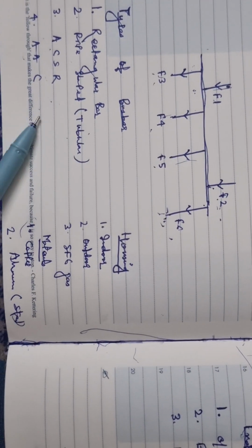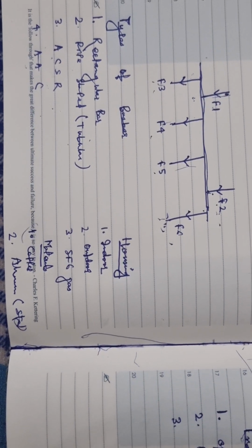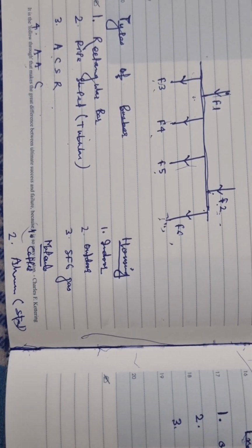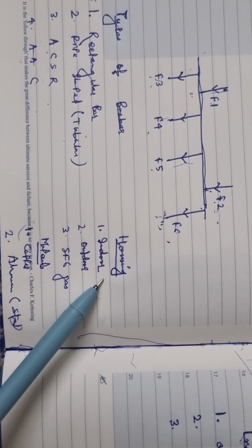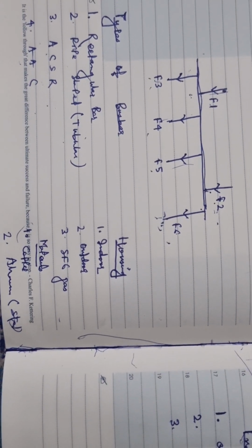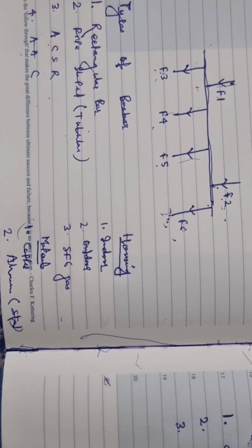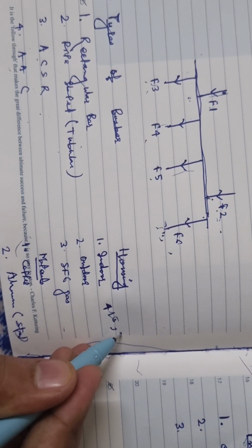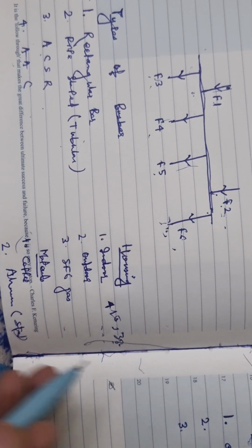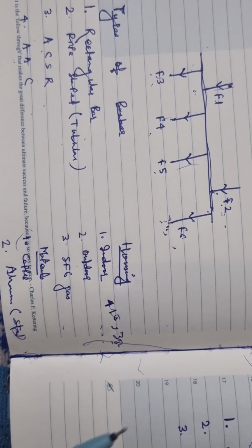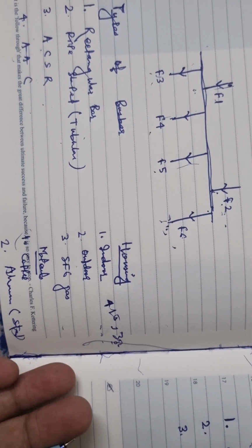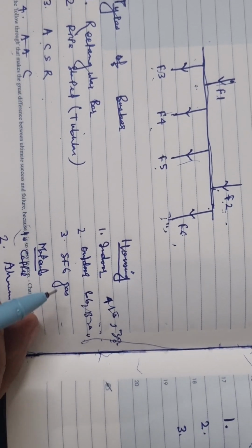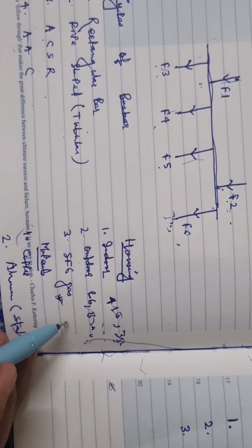Then for the bus bar schemes we are using, there is their housing. What are the different enclosures for it? We have indoor type, outdoor type, and SF6 gas type. Indoor type means inside a metal clad enclosure with suitably rated insulators. It is used in switchgear panels for voltage ratings of 415 volts, 3.3 kV, 6.6 kV, 11 kV, like that. Another is the outdoor type, the switchgear for voltages of 33 kV, 66 kV, 132 kV, 220 kV. Another one is the SF6 gas type, which is used for GIS systems.